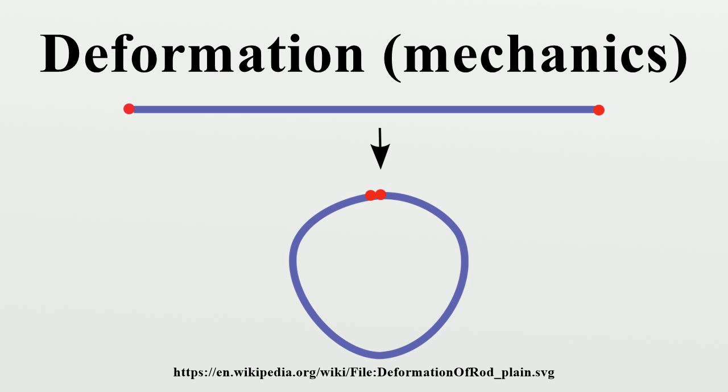A deformation has units of length. We could, for example, define strain to be the deformation minus the identity tensor, where I is the identity tensor. Hence strains are dimensionless and are usually expressed as a decimal fraction, a percentage or in parts-per notation. Strains measure how much a given deformation differs locally from a rigid body deformation. A strain is in general a tensor quantity.